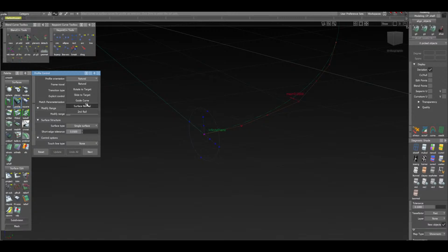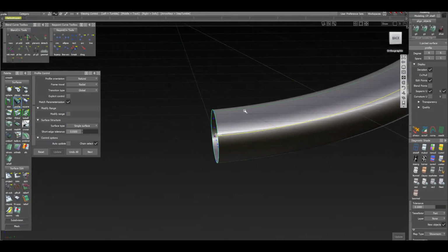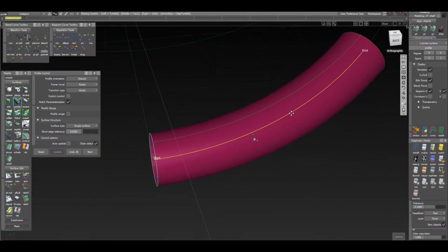intuition is telling me profile orientation. Okay, we'll just keep it to natural, just so that I know here. We'll click the circle, select curves. So it says here, select curves or surface curves for profile set selection. Click done to select the rail path. This is the rail path. And if I hit build, okay. So this is another option. We can use the profile tool to establish, like I said, a circle here, and then we use the fit curve to establish the axis. And we see that it's a 6x6 single span. We can go ahead and verify it's one surface by using colors here.